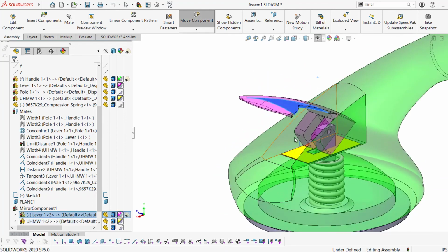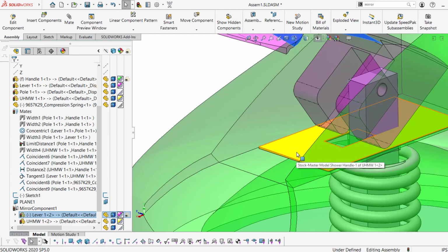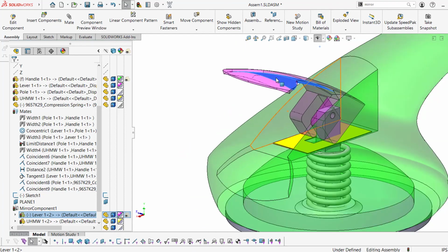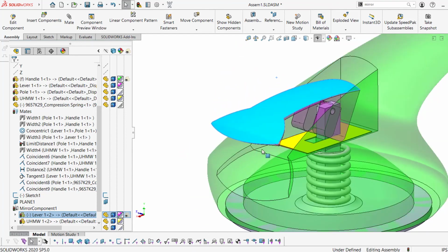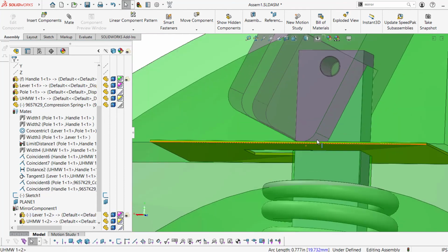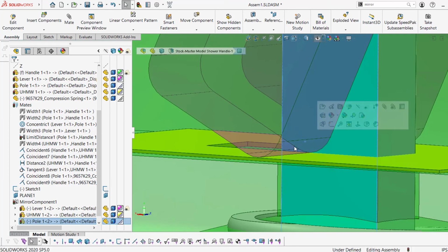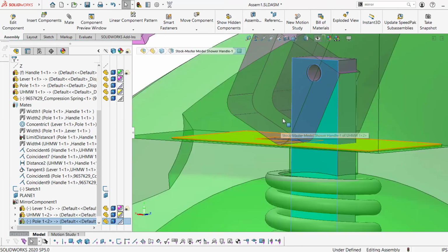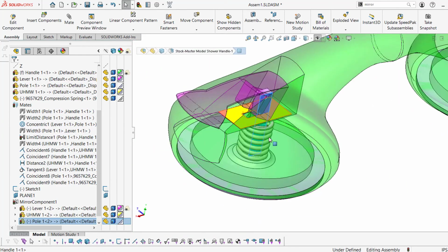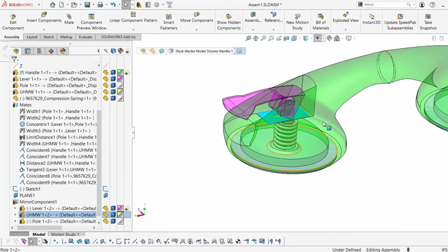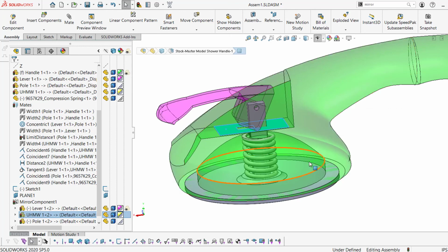So when I said we suspect, it's because we don't know for sure. I didn't really test the material properties, but it makes a lot of sense to put UHMW where the yellow part is. As you may notice, this part right here, this curvature of the pink handle, is going to come in constant contact repeatedly on this surface. And that's why it's a perfect place for UHMW.